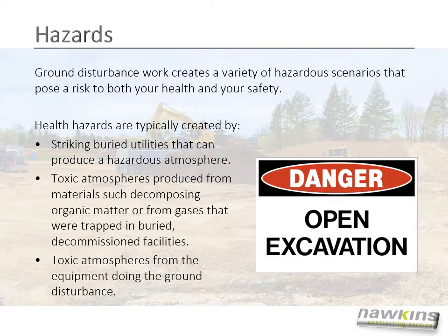Ground disturbance work creates a variety of hazardous scenarios that pose a risk to both your health and your safety. Health hazards are typically created by striking buried utilities that can produce a hazardous atmosphere. Toxic atmospheres produced from materials such as decomposing organic matter or from gases that were trapped in buried, decommissioned facilities. And toxic atmospheres from the equipment doing the ground disturbance.